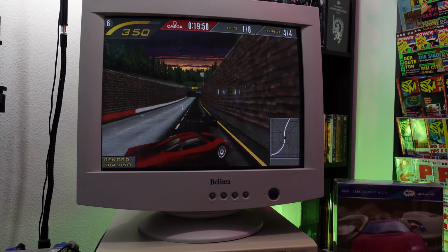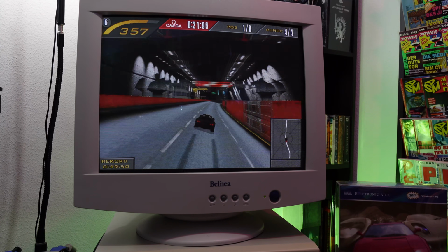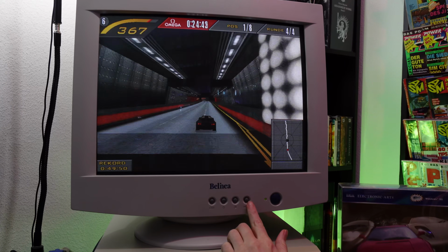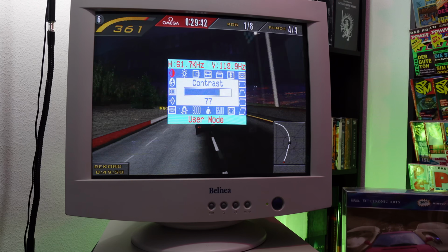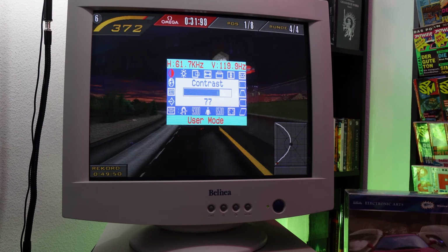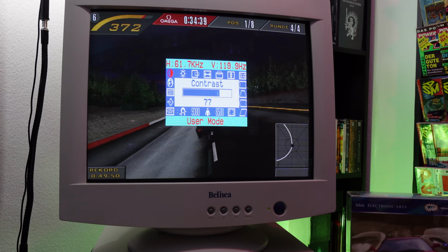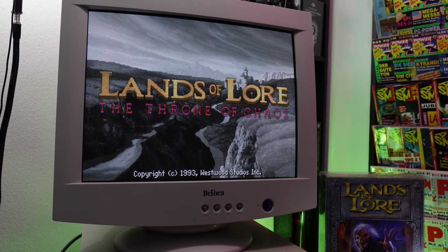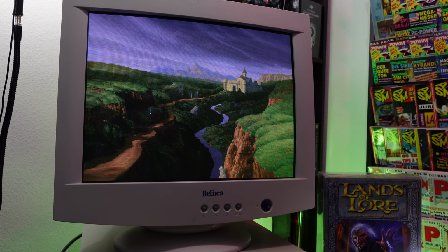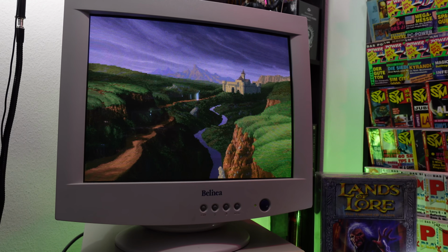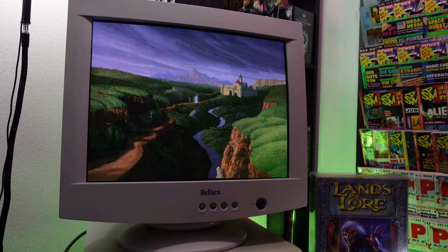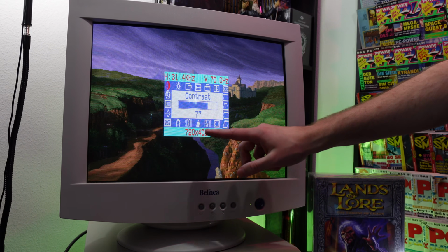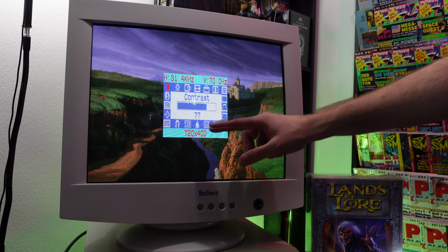And without going into details on how CRTs work, just know that these analog signals are then just displayed as they were. An additional conversion was not necessary, and it was also not dramatic if it didn't match a standard perfectly. The important part here to take away is that a tube screen had only very few restrictions regarding the format. For a retro PC with games running in DOS, which were released in the early 90s, this is especially relevant for the standard resolution at the time of 320 by 200 pixels, which is interpreted by the monitors as 720 by 400 pixels and getting shown at 70 Hz.